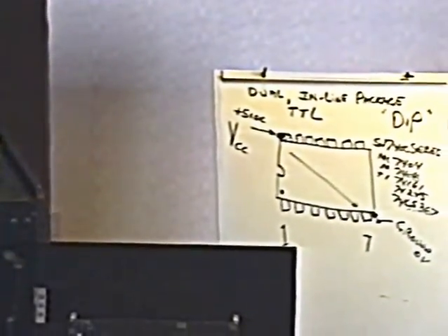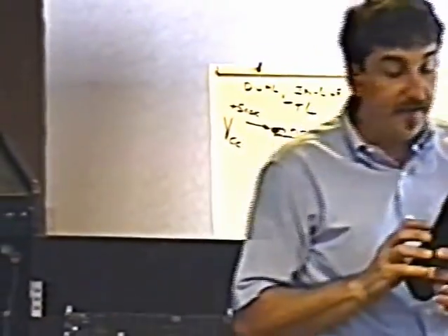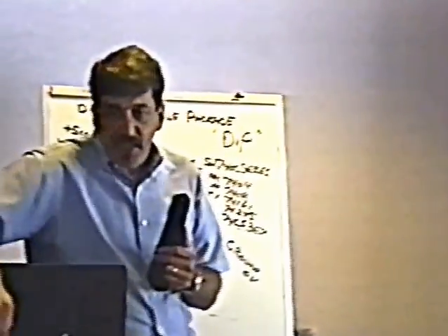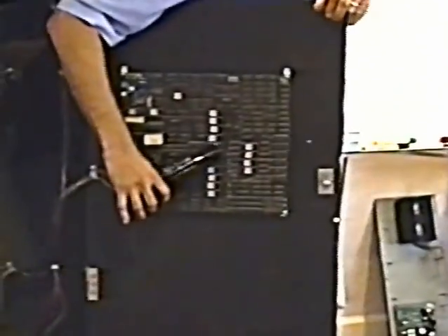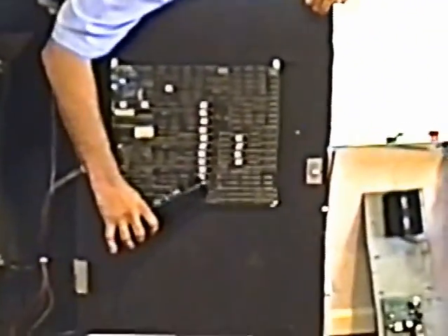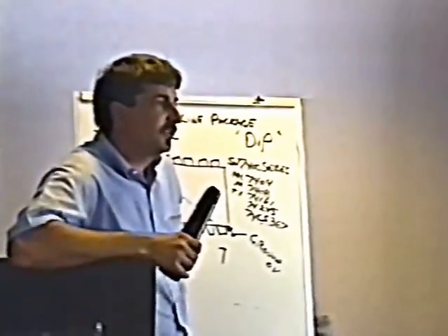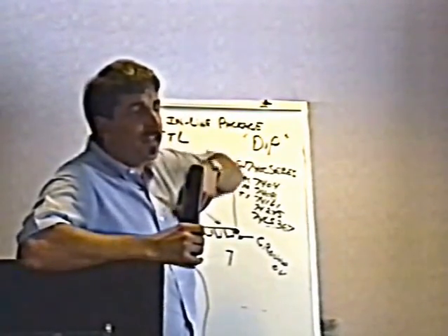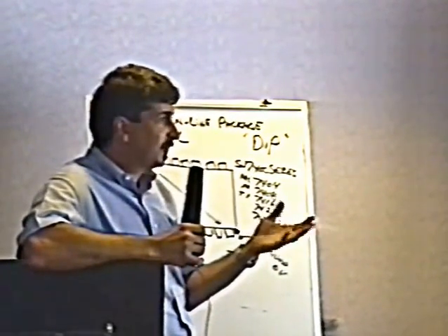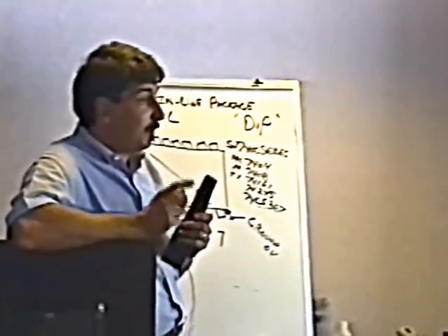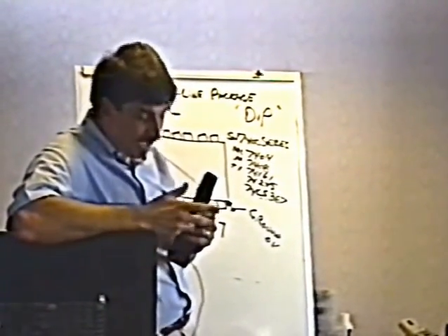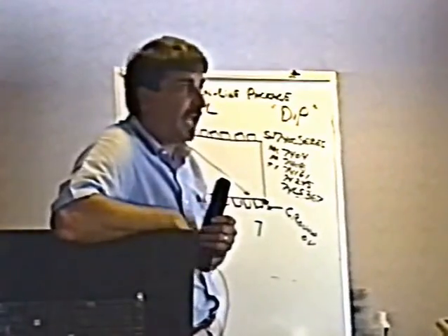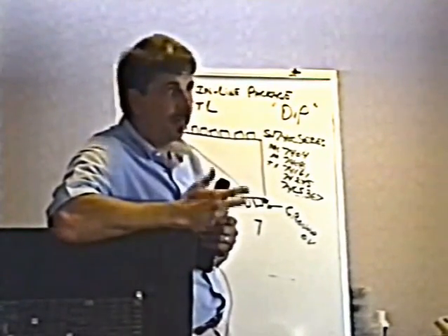Now, if that doesn't work, you do not have to give up. There's still another thing that you can do. Those big chips, these ROMs down here, I find lots of failures in those things. They're special custom integrated circuits, and they're actually programmed. They come blank to the manufacturer of the game, and the manufacturer programs them with certain information, and sometimes the programming bombs out somehow. I don't know why, heat or whatever, it just fails.